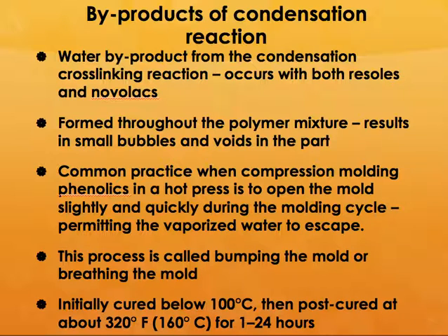So what is the problem with water byproducts in the condensation cross-linking reaction? It occurs in both resoles and Novolacs, and it is formed throughout the polymer mixture. So if you are not careful and if you don't remove it completely, it can form small bubbles and voids in the part. So if you do a cross section of your component and you see that there are big holes in there, that shows that lots of moisture has been formed